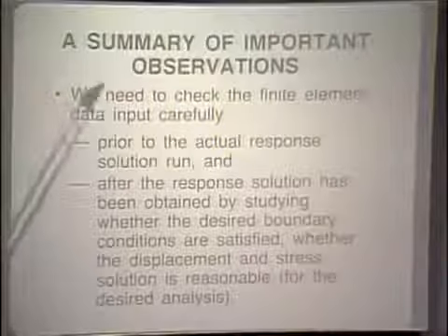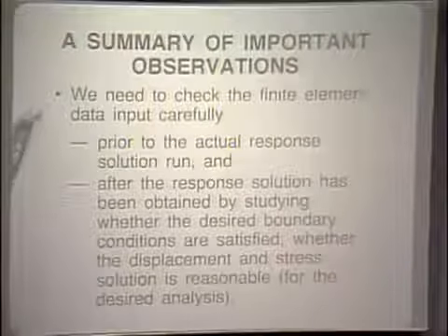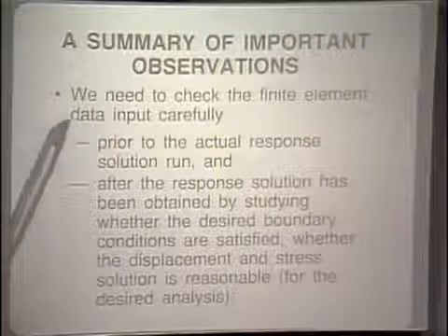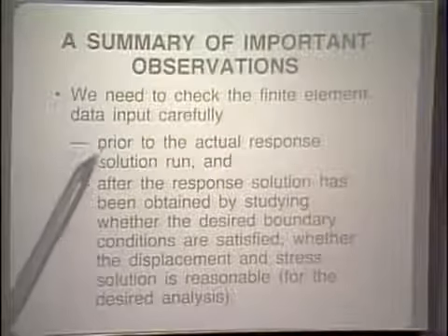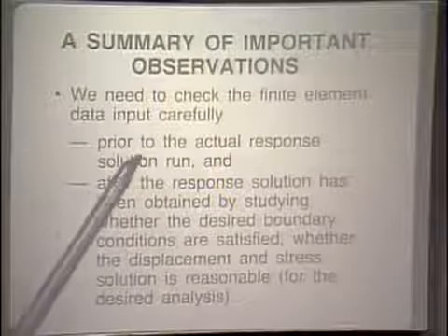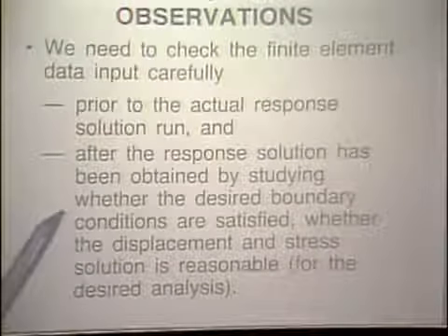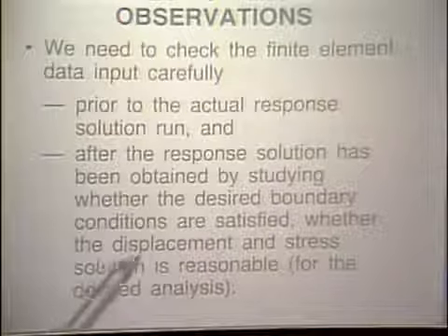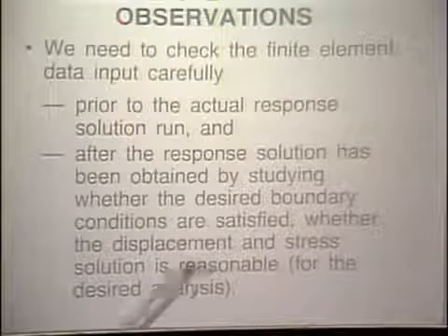With the analysis now completed, I'd like to look with you once more back onto 2 view graphs that we already have looked at earlier. On these view graphs, we summarized some important observations. And we said that it is very important to check the finite element data input carefully prior to the actual response solution run. That, of course, means plotting the data. And we have done so in our analysis. And after the response solution has been obtained, we study whether the desired boundary conditions are satisfied, and whether the displacement and stress solution is reasonable.